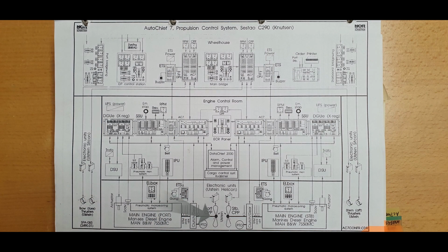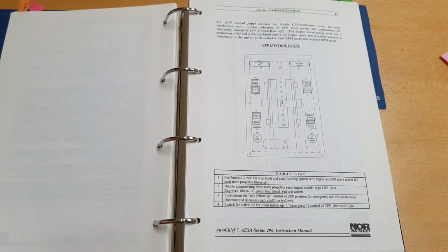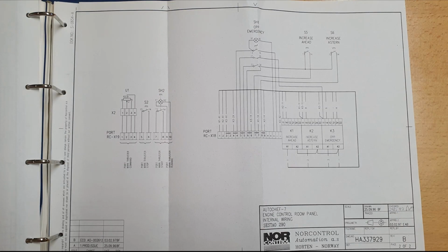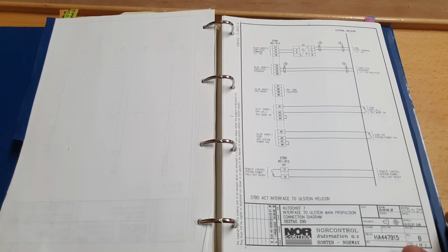Controllable pitch propeller, electronic control unit with microterminal, control panel in the engine control room. It receives the pitch signal from the maneuvering lever, aft thrusters and bow thrusters. Let's look at the electrical diagram of the maneuvering lever. Emergency mode push button and for pitch increasing, ahead and astern push buttons. And finally an important element of the system. This is a 4-wire potentiometer that gives a signal of 10 volts of different polarity.